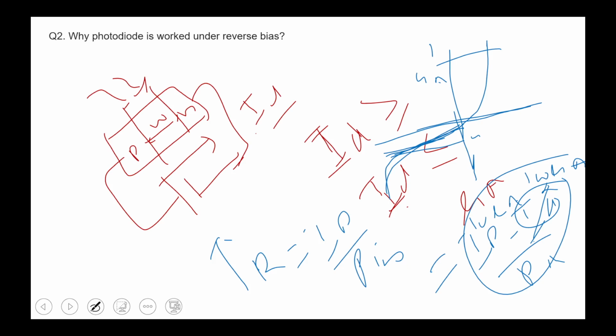For any device, there is dark current. We have not applied anything on it; we just bias it at 2 volts or 1 volt, and it just gives current. Anything with just the material will not be useful for us, because we have to detect light, and the current should be generated when the light is detected, only due to the light.